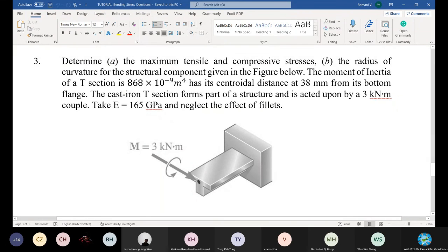Last time, the very first was the rectangle. The second one was the I section. Now we are going to solve for the T section. It's interesting how the profile keeps changing, right? Where the maximum, where the minimum, and which profile is significant in your design. This is how the engineers will design. When you go to size the reinforcement, after the shear reinforcement, shear bars, everything is considered based on this type of analysis.